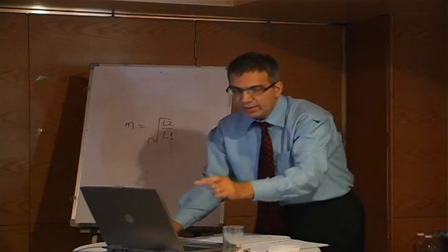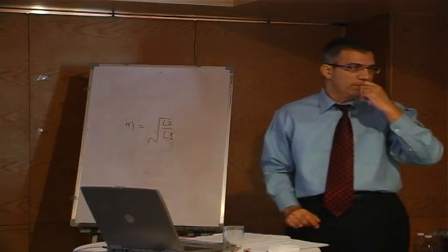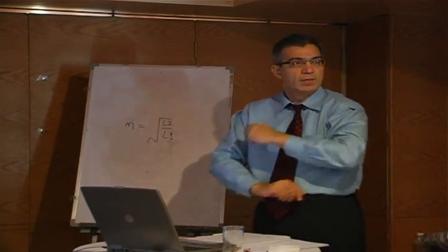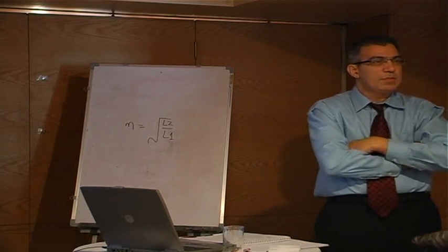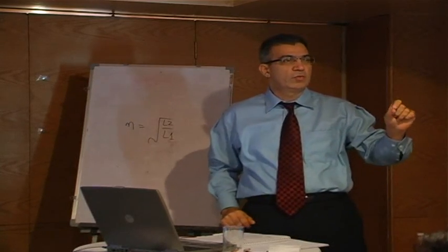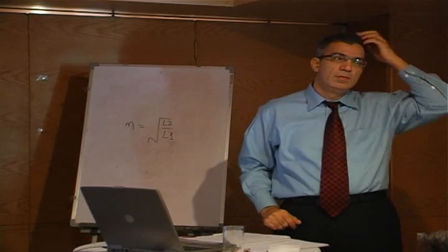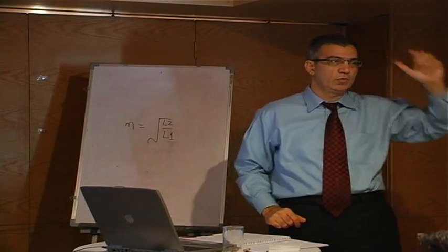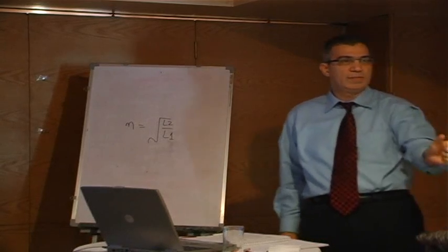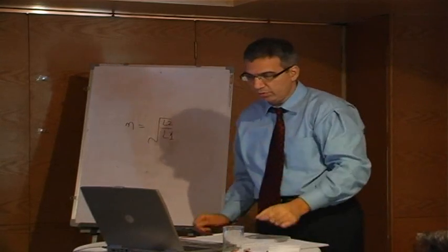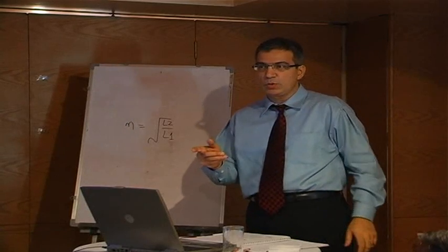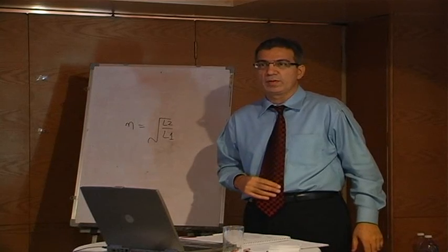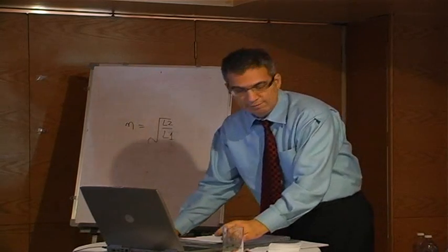So you can see that they are essentially offset by 180 degrees. But there is also a gap between the two. It's not a dead zone, because the duty cycle is 0.4. So after 0.5, the second pulse will start. Essentially this doubles up your ripple frequency.